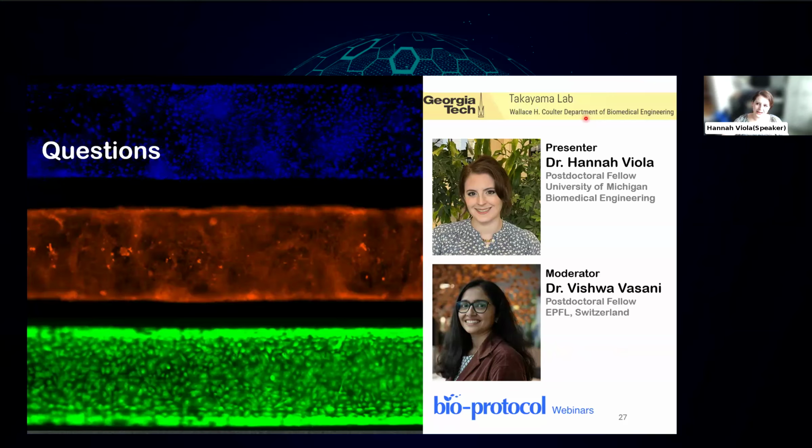And then the coolant. We used to use a lubricant provided to us by the fabrication core. I stopped using it because it didn't really seem to do anything. Have you used a lubricant, Vishwa? No, I think our devices are usually air lubricated, so we have a constant stream of air on the tool, and that removes any chips and prevents them from clogging around the tool. So it's technically air lubricated, but no separate coolant. At least I did not need one.